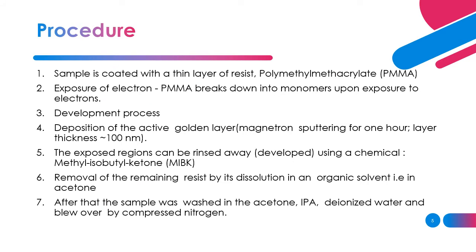First, the sample is coated with a thin layer of resist, which is PMMA, the same as in X-ray lithography. Exposure to electrons breaks down the PMMA into monomers.